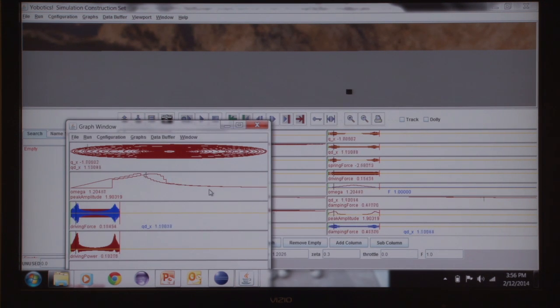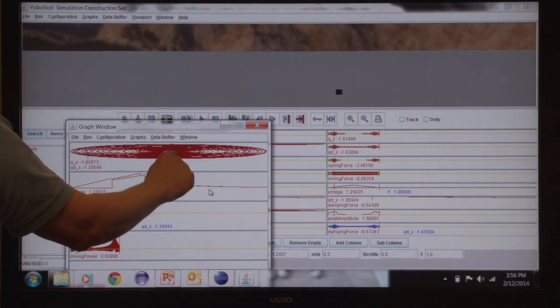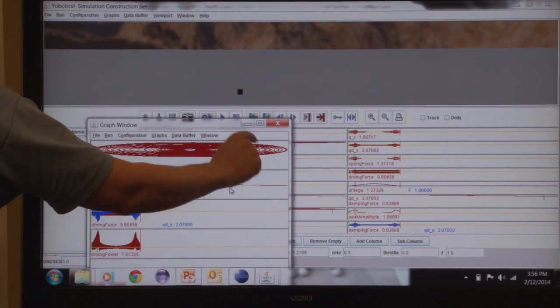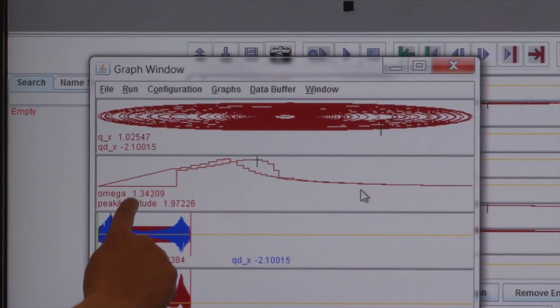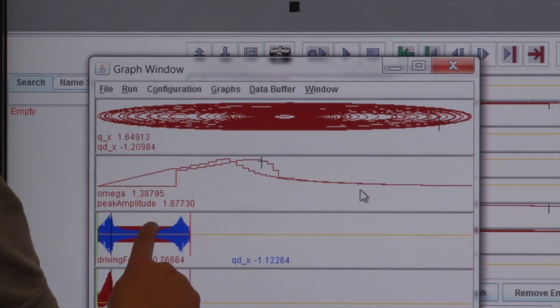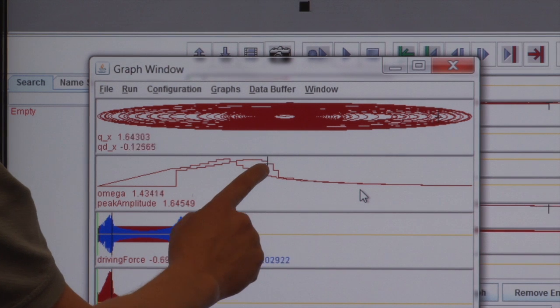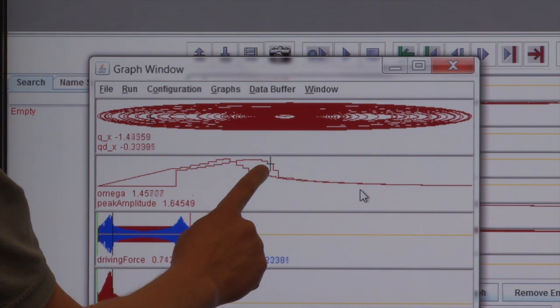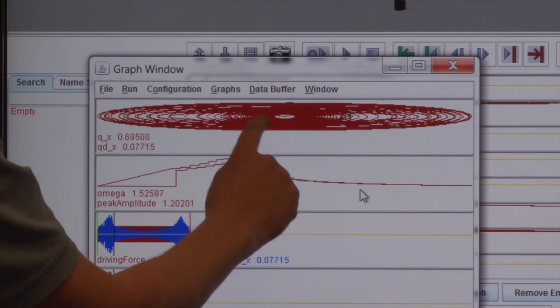The phase plot on top? Yeah, so if you look at this phase plot, it started out going out, as it hits resonance it'll have the highest amplitude, and then it'll come back in as it goes to really high frequency. But in this plot you can see the frequency versus the amplitude. It was just riding up this curve, and this is where it's going to drop off. Now it's too high of a frequency for the amplitude I'm giving it, and you see it spiraling in.